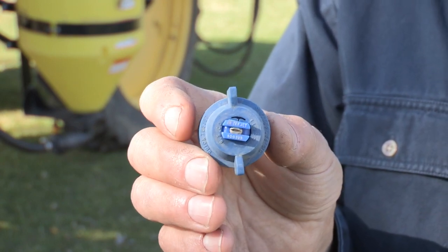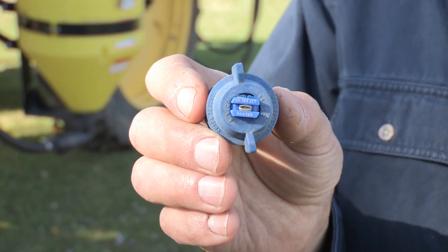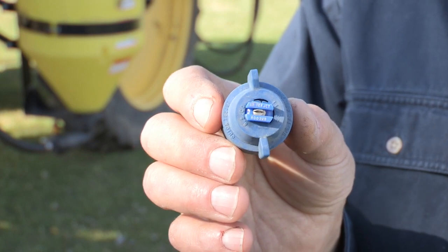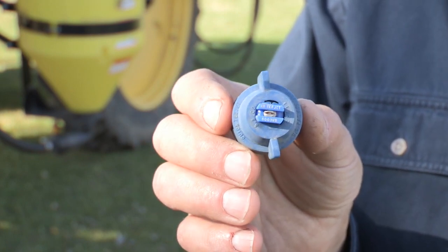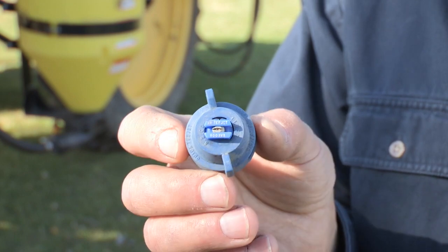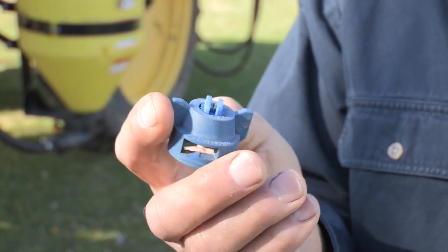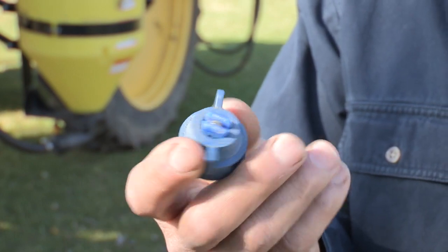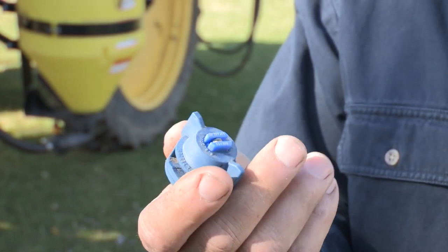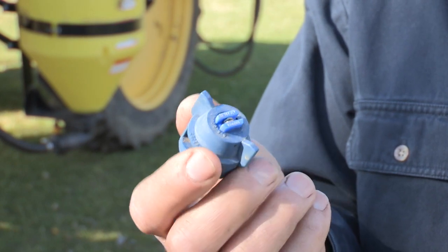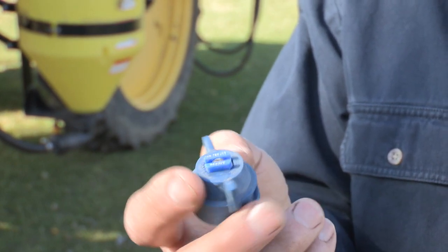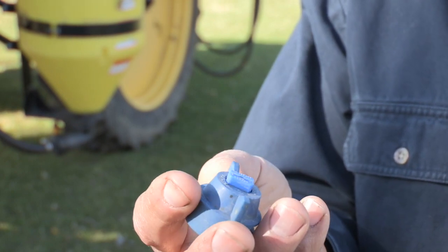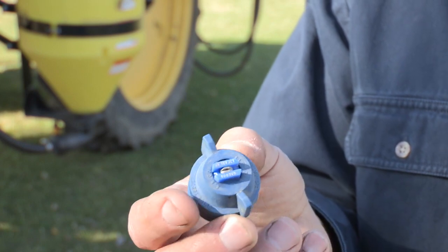And the 03 is important to note because at 40 psi, this nozzle will put out 0.3 of a gallon per minute. The blue designates kind of a medium coarse droplet size. That's kind of an industry standard. They've got various colors for nozzles, and the V is T-Jet brand type of color coding, Visicolor, and the S stands for stainless steel.